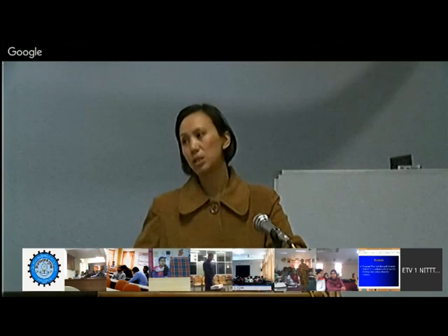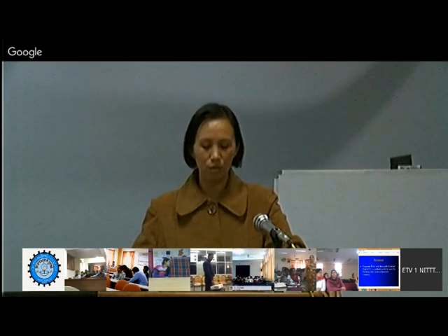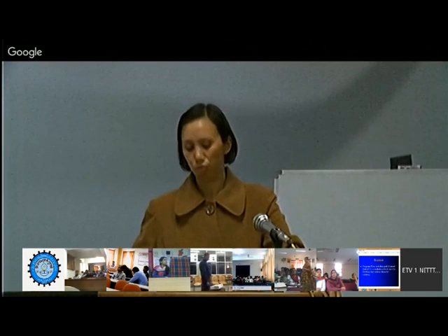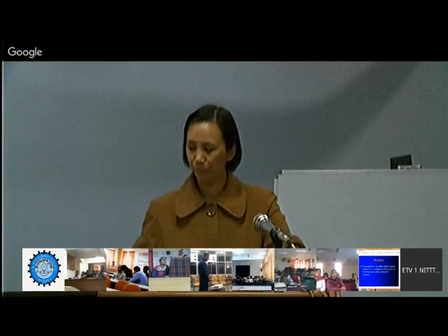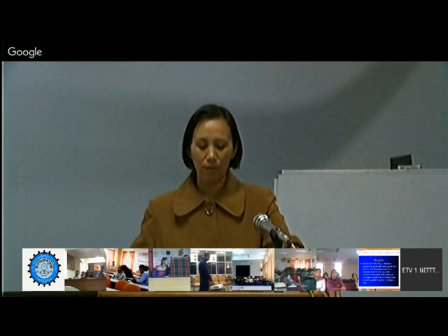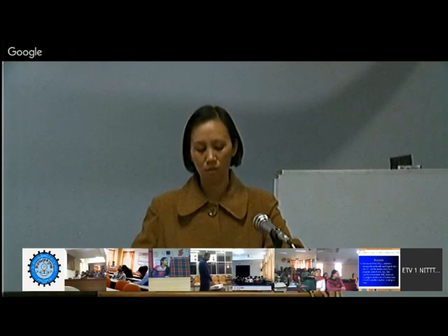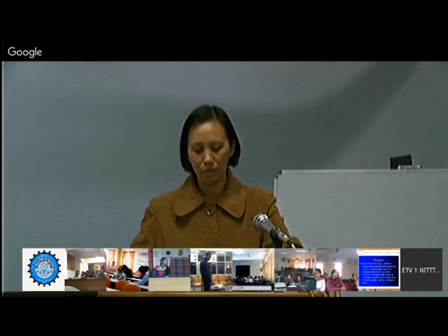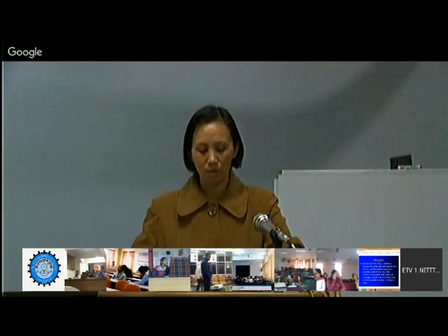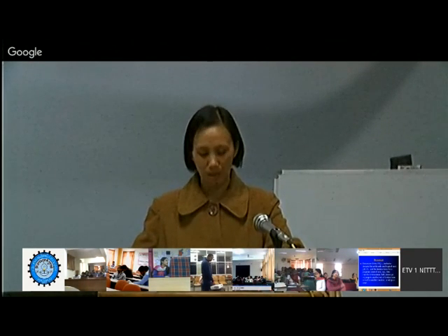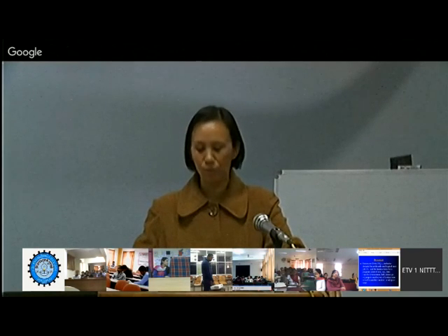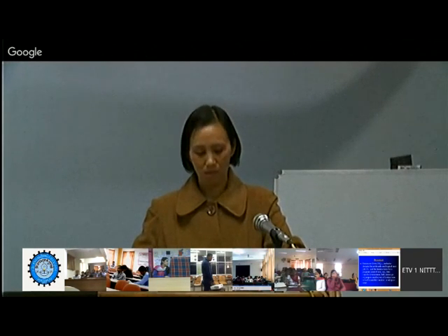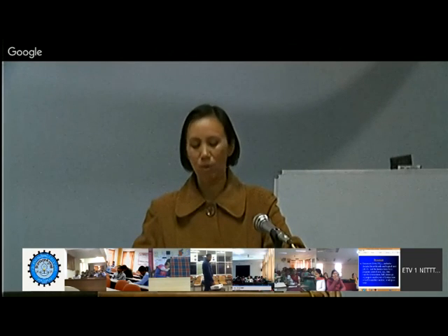Now the processor consists of two main units, that is your program flow and the data path control unit. This part includes a fetch unit for fetching instructions from the memory. Then you have your execution unit, which includes the circuits for the arithmetic and logical unit, and for instructions for program control tasks. Say, for example, your data transfer instructions, halt, interrupt, jump to another set of instructions, call to another routine, or sleep or reset.